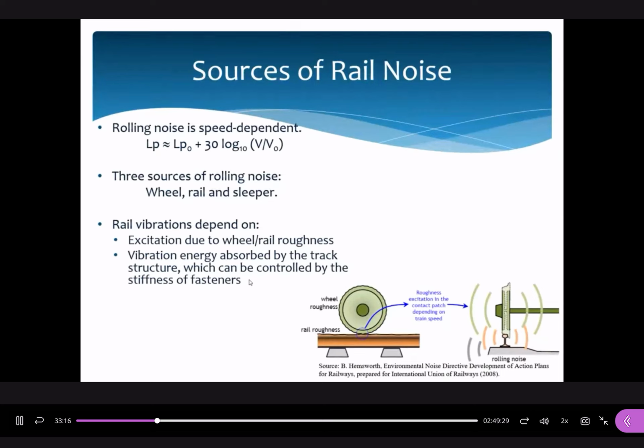So when you compare the low vibration track and the floating slab track, there are two diagrams here. The first diagram is that we just put an isolator below each wheel. And in the floating slab track, we design a structure, a floating slab, and then below the concrete slab we still install isolators. This is the major difference between the low vibration track and the floating slab track.